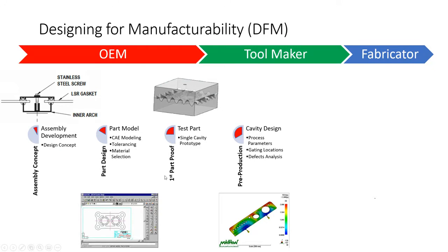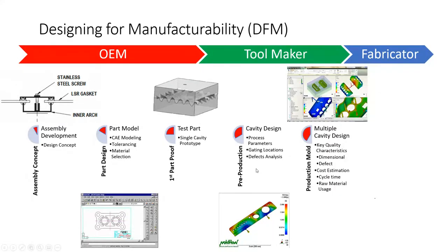Here we have to look at the cavity design. In those cases, we are using things like MoldFlow, which is CAE software that shows us the flow of the materials throughout the material path in the injection machine, through the runner system, and through the mold cavity itself. These are very important because from the very get-go, we can look at process parameters, gating locations, defect analysis, and more.